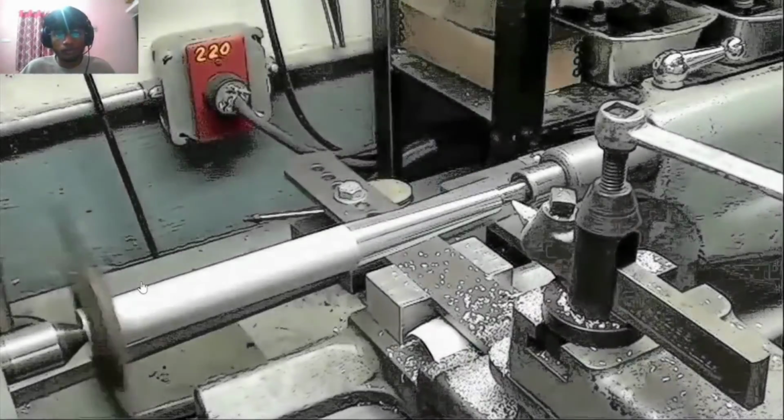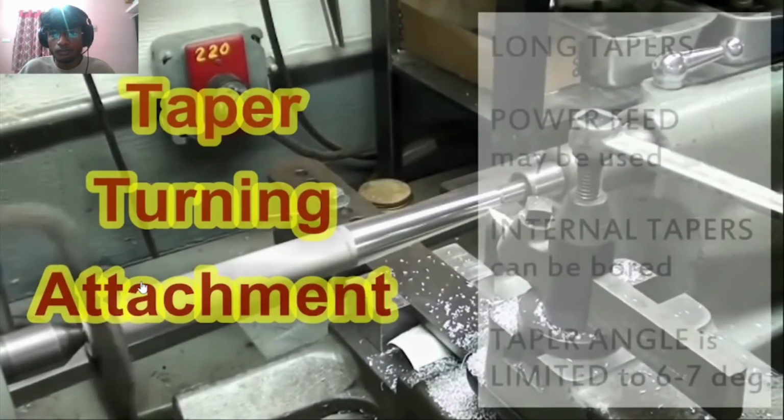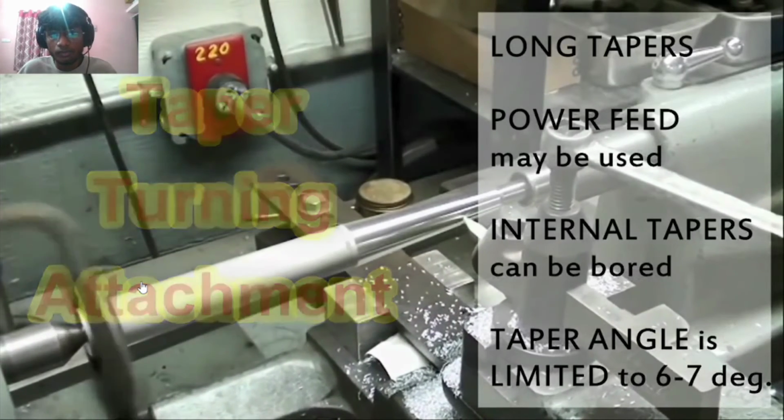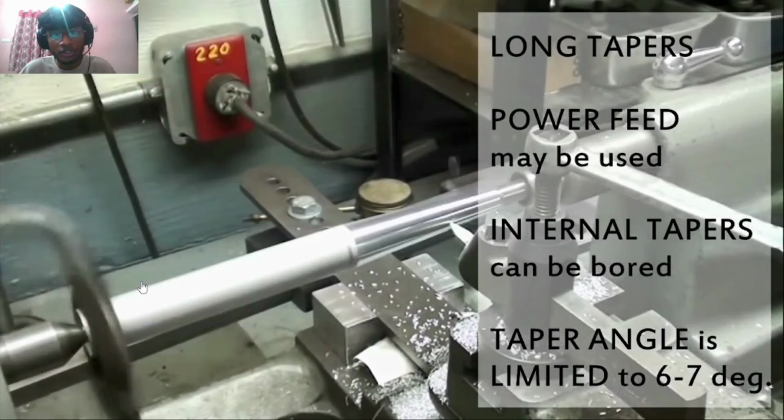This video is about taper turning attachment used in lathe machines. This is preferred in case of long tapers, especially when power feed is to be used. And yeah, in the previous method we might have seen we can only give taper for a small distance, right? But in this taper attachment method, we can give very long tapers, and internal tapers can be bored. And if you are wondering what the taper angle is limited to, it is limited up to 6 to 7 degrees.